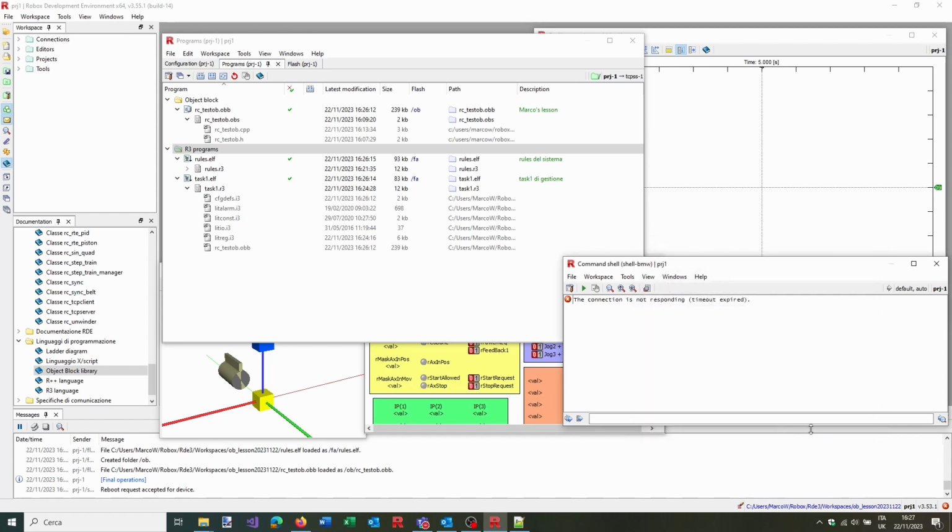Now the RP2 has a reboot, and I can see the normal alarms. Maybe we can also see from here, ALS. Yeah, user register loss, alarm history loss, unable to read persistent global variables. That's because I have put a new project and the RP2 is understanding this.